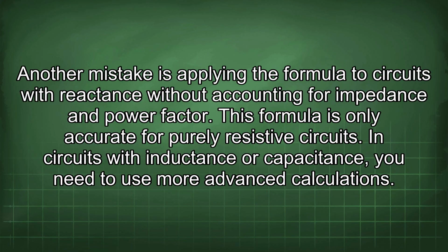Another mistake is applying the formula to circuits with reactance without accounting for impedance and power factor. This formula is only accurate for purely resistive circuits. In circuits with inductance or capacitance, you need to use more advanced calculations.